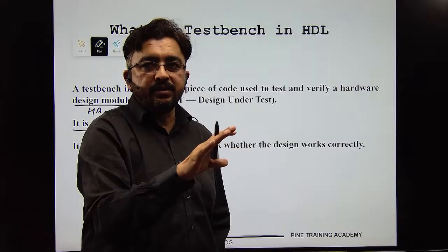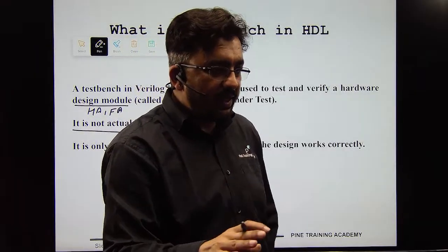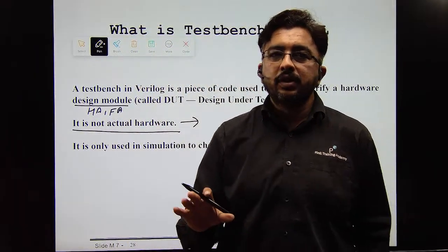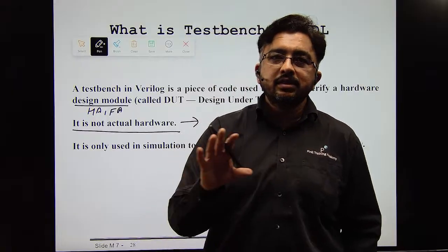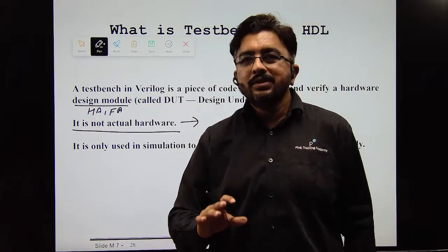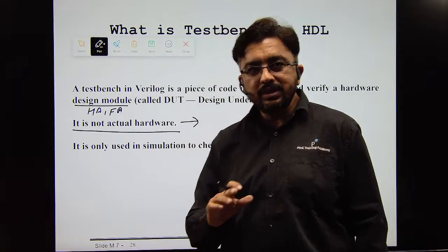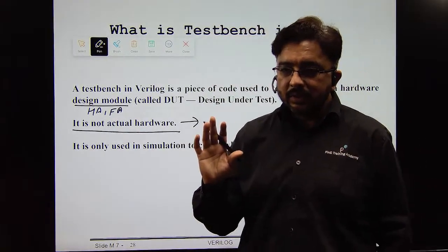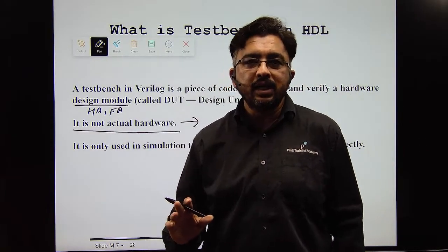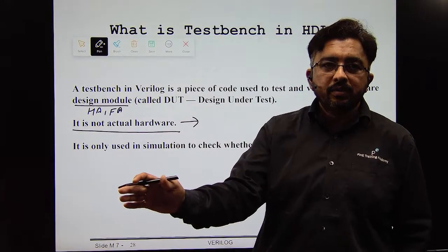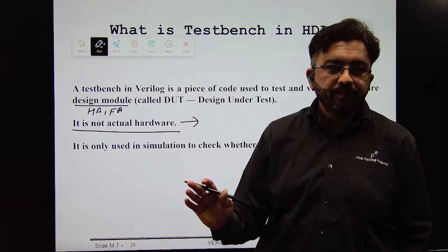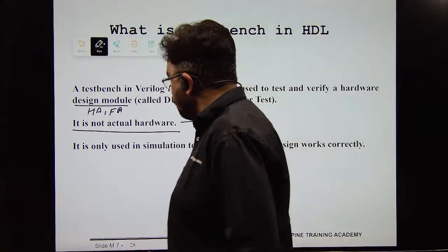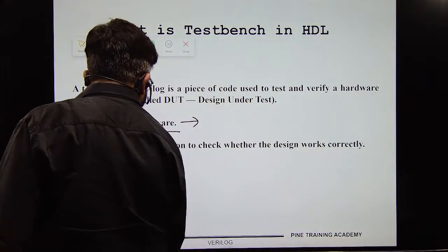You are not generating any netlist, any hardware schematic, or any synthesis for that. So this is very clear: the test bench is not giving any hardware with respect to the gate level. It is only used in simulation to check whether the design works correctly.